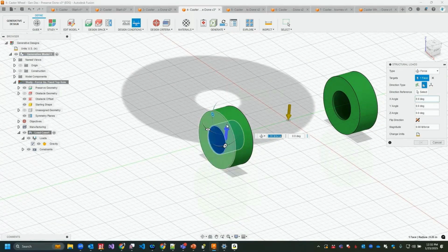Of course, we've got the rotation icons here that we can use to rotate our loads around. That would be how you would add the negative 30 and 30, by using the degree angles here. That's how you would add those different loads in there. You can add the loads at different angles inside of there. I'm going to hit that, and we'll say this is a magnitude of 200 pounds force.